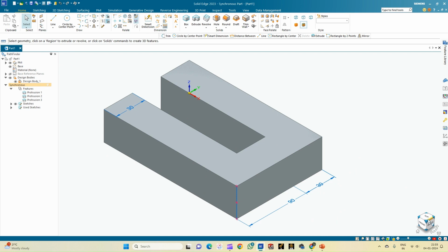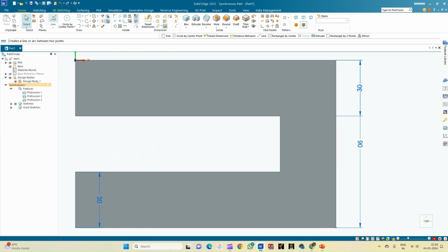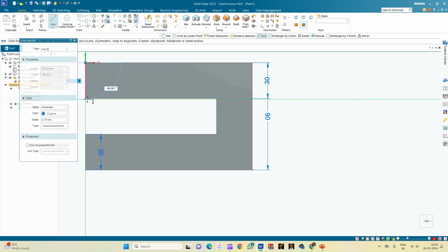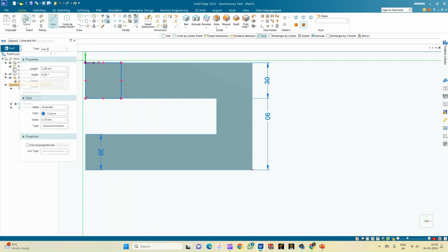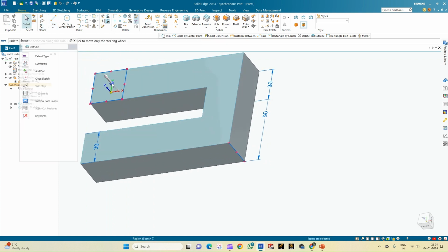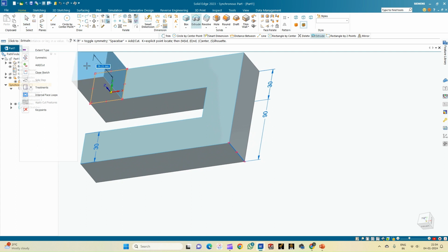I'll be selecting this plane. So I'll select the top view. I'll select this particular part. So this is 30 cross 30 again. So let me select this square of 30 cross 30 and extend this to a total height of 100. So since this particular portion is already 30 mm, I have to do it as 100 minus 30, which is 70.